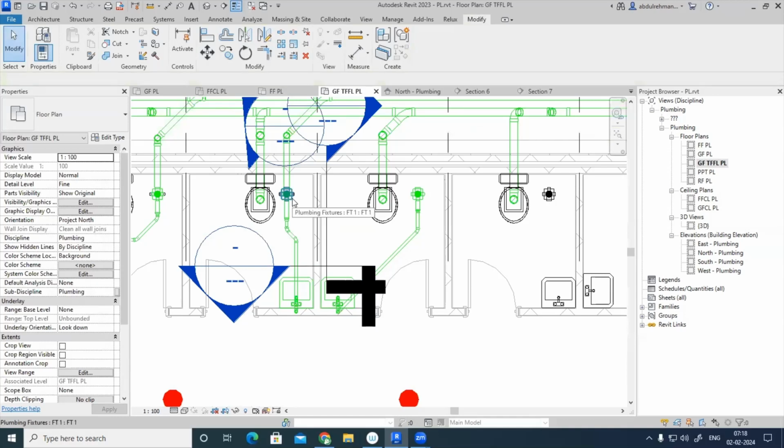Then you can do one thing. We are having Nahani trap. Means a single floor drain with the Nahani trap that will come, that we can propose. So floor trap cost we can avoid. But if there is a wash basin, definitely a floor trap has to be proposed. Individual cubicle, separate floor trap.